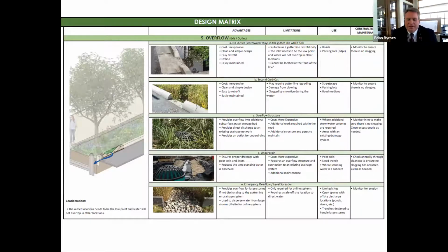Yeah, we did one of these downtown, and I only had like 15 feet to do it, and there was an existing catch basin there. So we blocked up the catch basin and let the water come off instead of going to the catch basin. And again, not a lot of room, sidewalk on either side. It came through, and then we just put a pipe in as an overflow and piped it to the drain, because the drain pipe ran right along the curb line. So we definitely have used this pipe thing before when you have very little space.